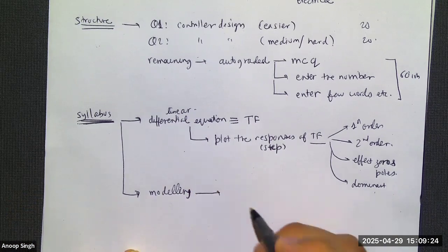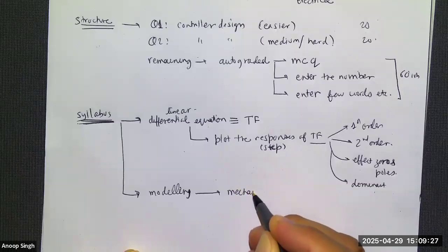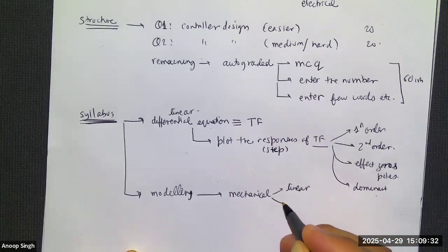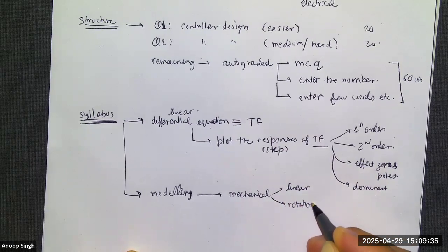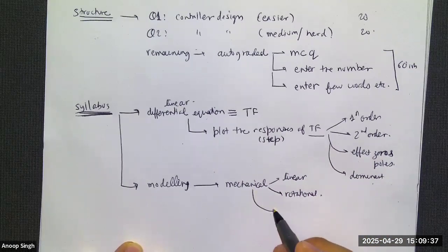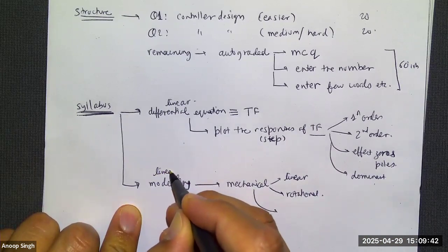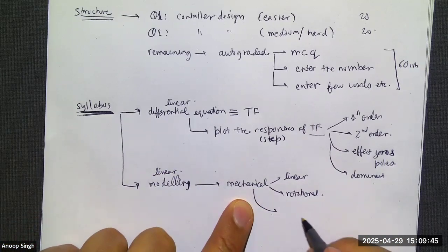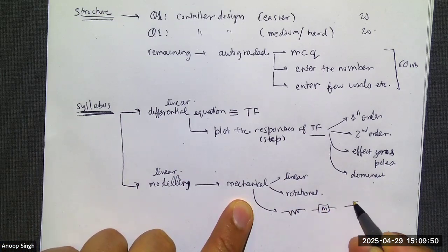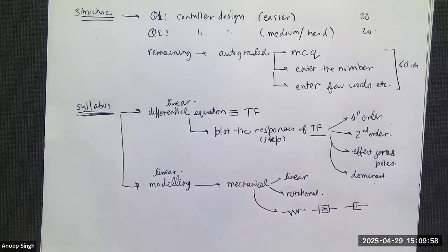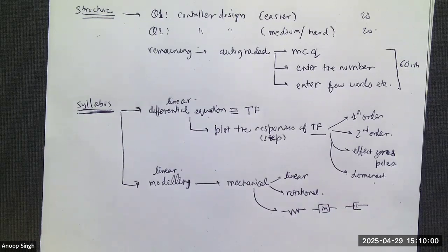So in the modeling, we talked about mechanical systems. They were the linear or translational mechanical system, and then the rotational mechanical system. We specifically talked about how, if you're sticking to linear systems, the mechanical systems could always be boiled down to a combination of spring, some mass, and some damper, or the rotational version. So rotational spring, rotational mass, which is moment of inertia, and rotational damper. So it's going to be all combinations of this.